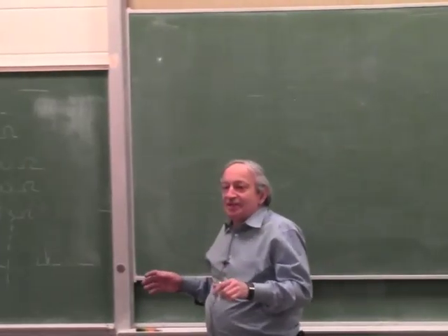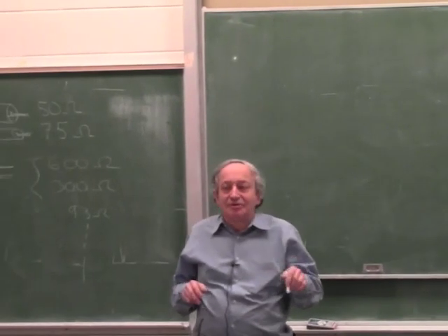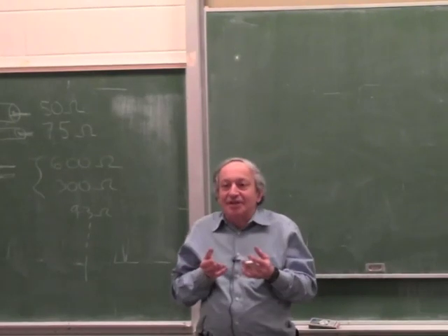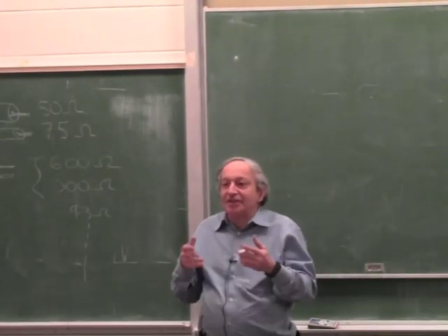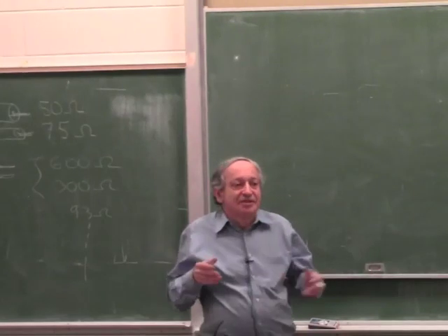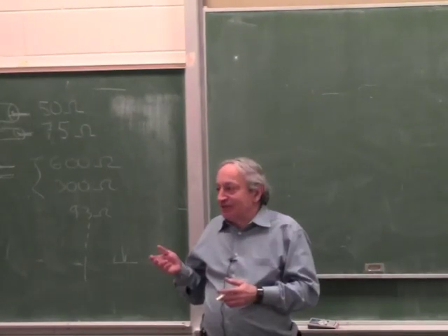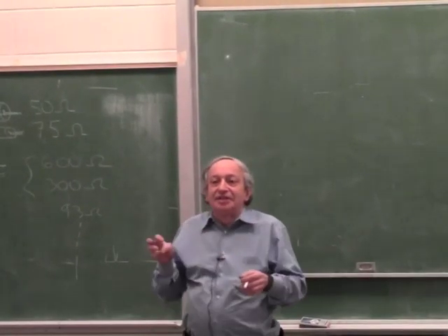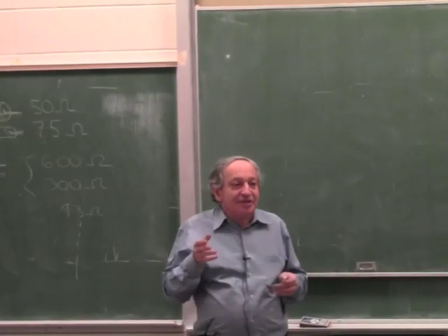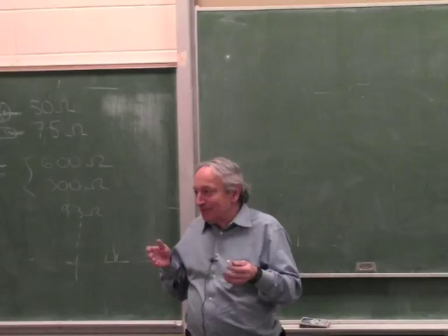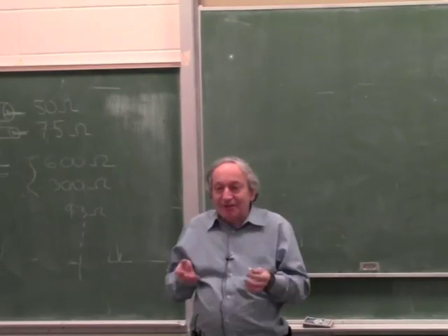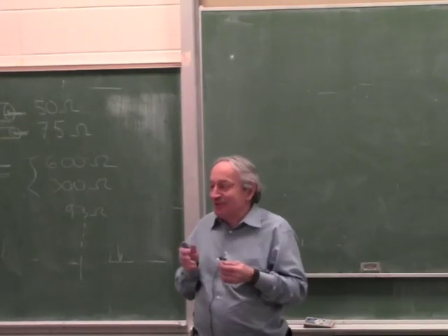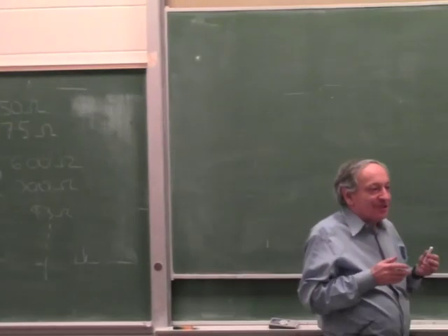And that's very important to understand, and reminding you of the demo which I gave you last week, I had a sealed metal box, all metal all around, and it had a coil and an LED inside, and the LED was lighting up when I put it in a 60 Hertz AC electromagnetic field. Right? I had an electromagnet plugged into the 60 Hertz. When I held it next to this box, the LED lit up. And to light up an LED, you need a lot of volts, like 3 volts, in this case a blue LED. So this little box, although it was all metal, there was no problem generating 3 volts inside. So that's very worrying, which means this whole concept of shielding has to be treated with great care.